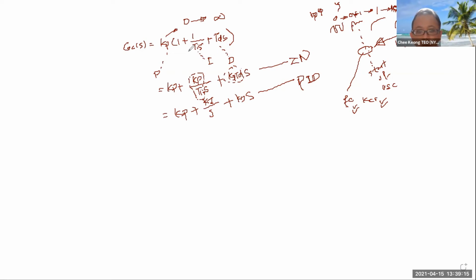Do take note that in his condition, when he varies the gain, he sets Ti to infinity and Td approaching 0. When Ti approaches infinity and Td approaches 0, you are getting rid of the I term and the D term. You just use a Kp term for your experiment. When it starts to oscillate, that is your undamped case.